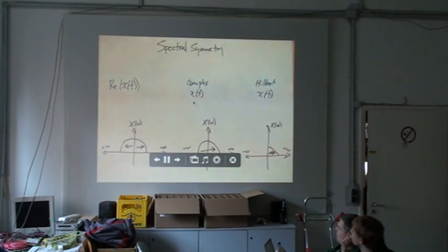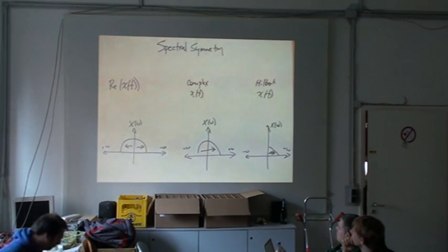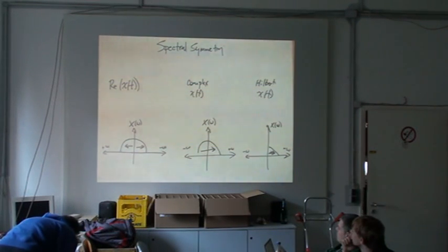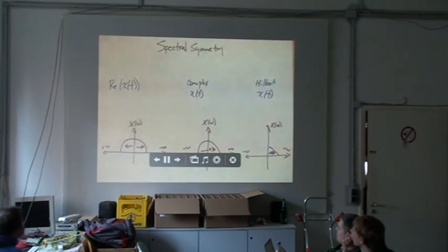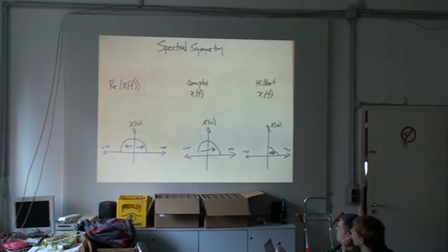What the FFT really wanted was a complex valued input. You put in n complex values, you get out n complex values, you get out just as much information as you put in. And what that means in the frequency domain is the spectrum is no longer symmetric. There's no redundancy in the spectrum anymore. Your negative frequency part of the spectrum is not the same as the positive frequency.